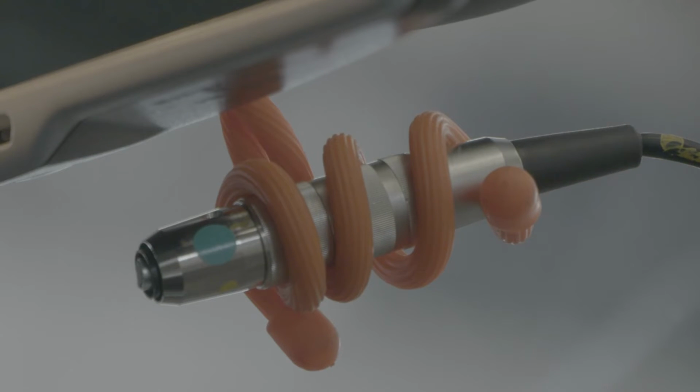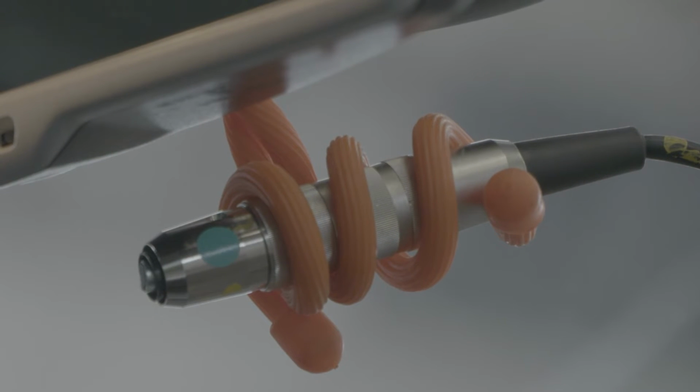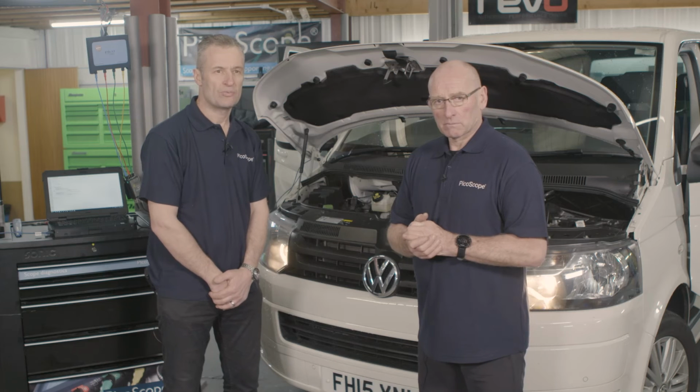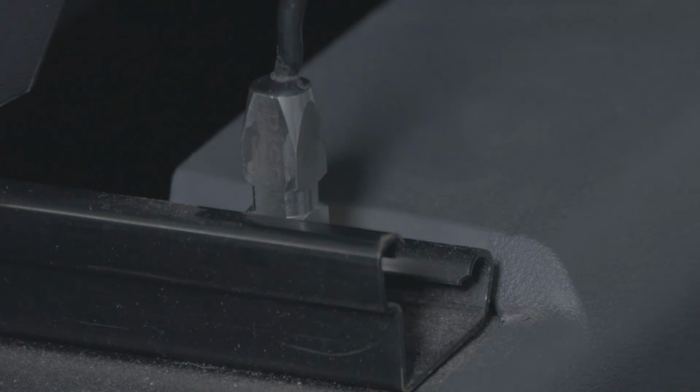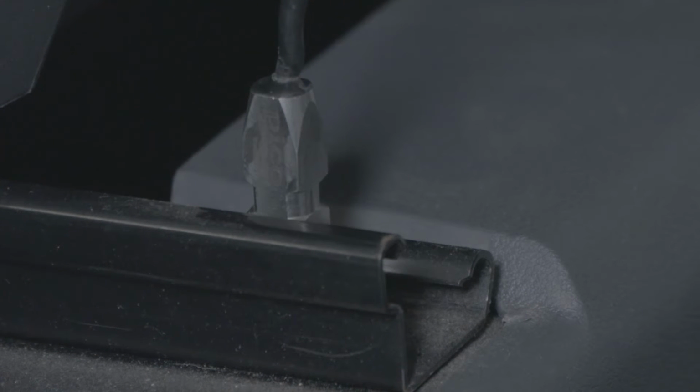So what we've done here with the van is simulated exactly what you saw in the animation. We've introduced a deliberate imbalance to the cooling fan. We've also then introduced the microphone into the cabin. So not only will we measure the vibration, but we'll measure the sound, which, remember, is one and the same thing. The microphone and the accelerometer both detect the vibration, the sound generated, and display them differently but at the same frequency. So we can use either or in this scenario.